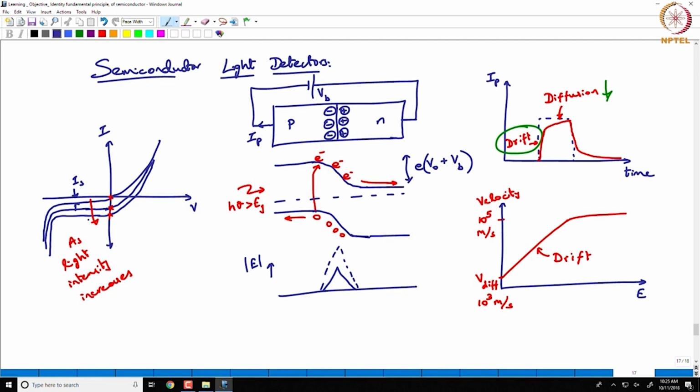That accounts for the electrons or holes you would lose on the other side as well. They are not actually seeing the external circuit, so they don't contribute to the photocurrent. So there will be a slightly lower current generated at 0 bias compared to some higher bias voltage.